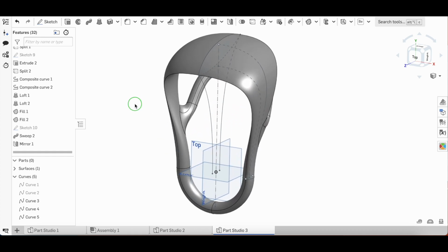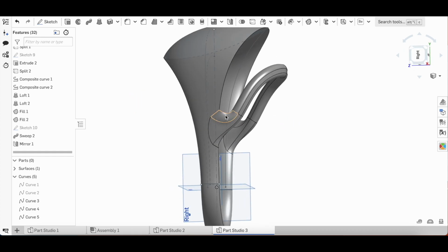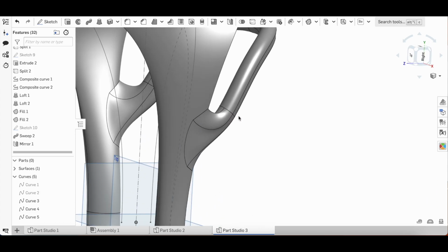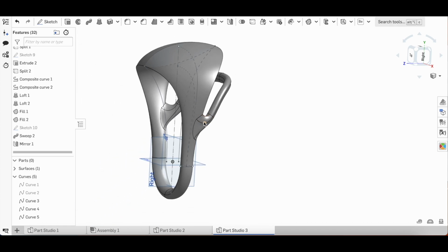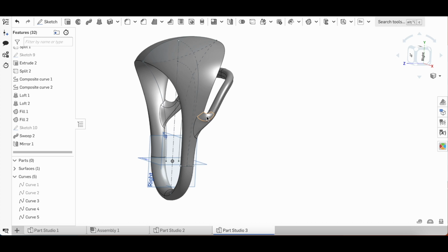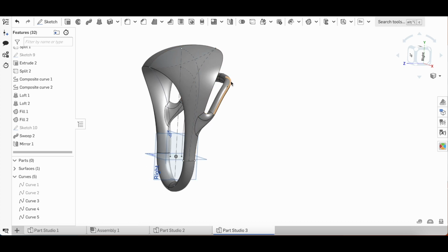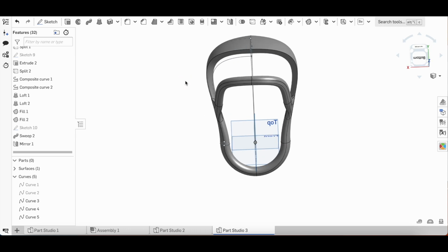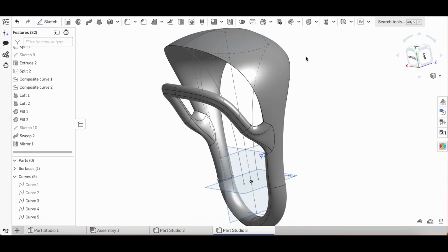And that's really it. So again, you can use this blend technique in a lot of different places. Basically, if you have, say, a six-sided shape that you're blending into something like this, you just want to make sure that when you cut through or when you're bringing in your loft features, you have 6 sides per side, and you blend those all together. Usually you don't want to do something that requires that many faces, but something like this will usually work in a variety of parts and features that you're trying to make.